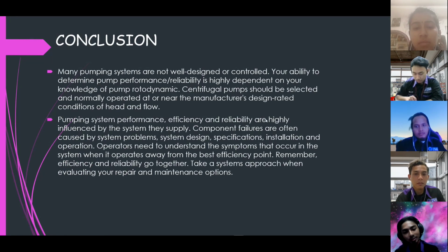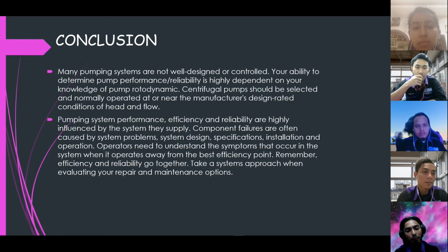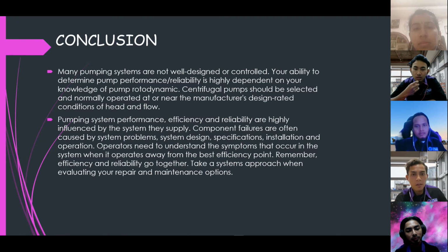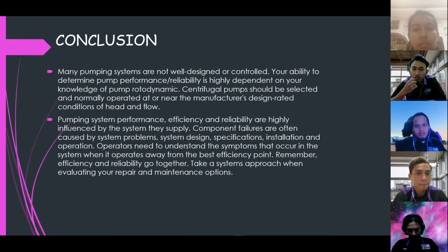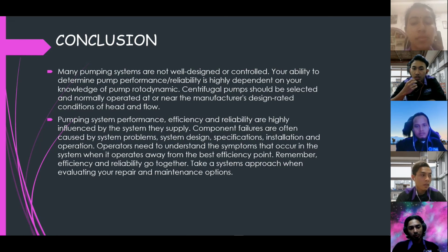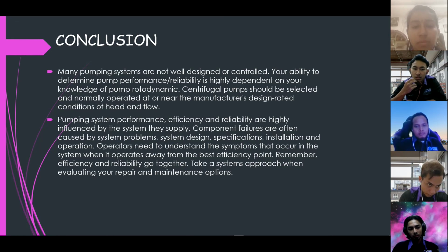Okay, for the conclusion, we can say that many piping systems are not well designed or controlled. Your ability to determine pump performance or reliability is highly dependent on your knowledge of pump rotodynamics. So a centrifugal pump should be selected and normally operated at or near the manufacturer's design rate condition of head and flow.